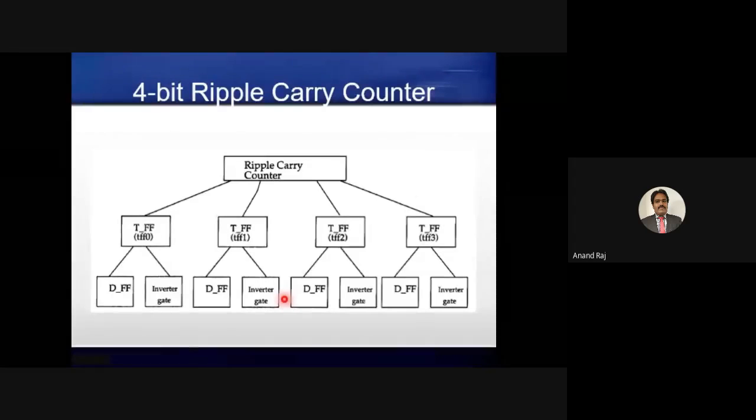Further, if we think of the bottom-up design methodology, we could build the D flip-flop using AND gates and OR gates, or you could build the D flip-flops using transistors, which form the leaf cells. So the bottom-up and the top-down approach meet at the D flip-flop level.